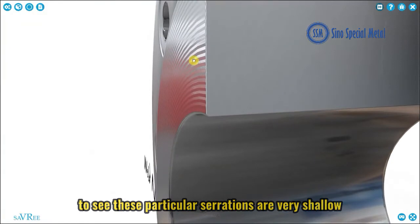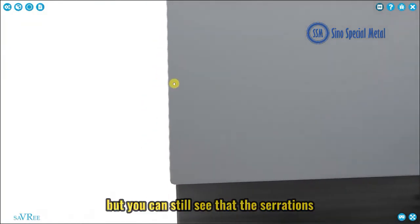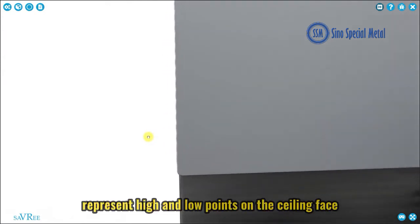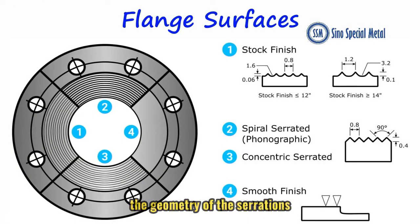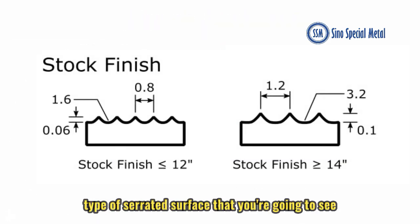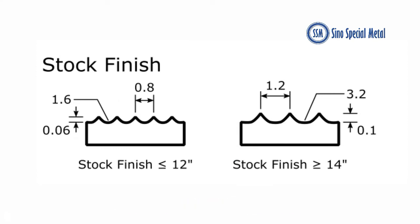These particular serrations are very shallow, but you can still see that the serrations represent high and low points on the sealing face. The number of serrations, the geometry of the serrations, and the way that the serrations are cut onto the flange depends upon the design. The stock finish surface is the most common type of serrated surface that you're going to see. And you can see on this diagram that there are different types of stock finish depending upon the size of the pipe.